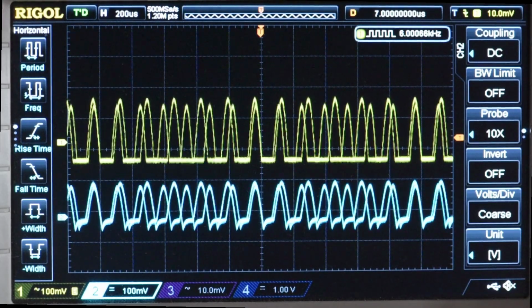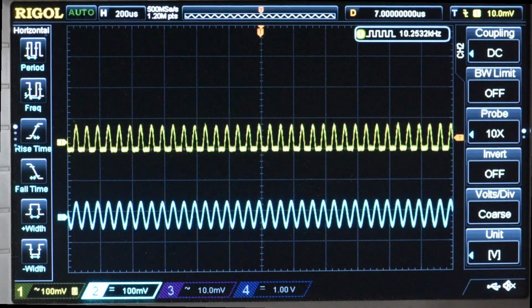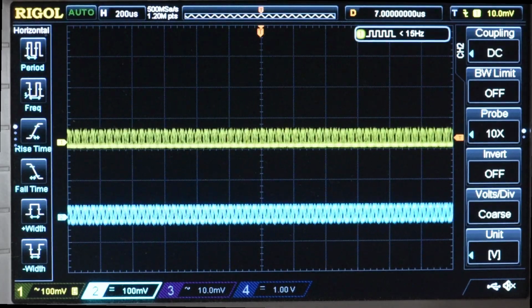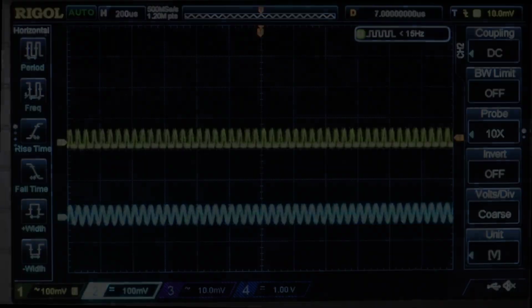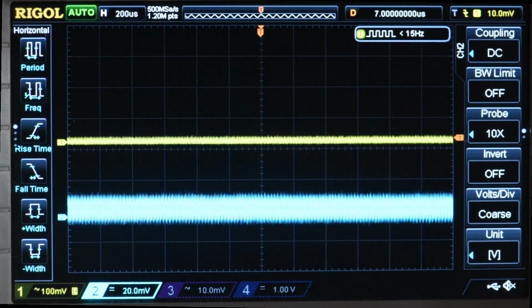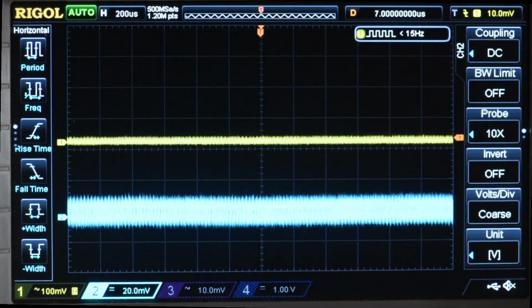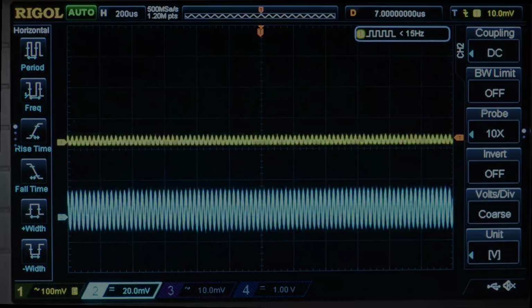That should give me about the same frequency response as the voltage section. The yellow trace is the output of the DAC buffer. This time the blue trace is the input to the ADC. By 20 kilohertz, well down in amplitude. Just the faintest bit showing up in the output at 60 kilohertz. So if I can sample at 120 kilohertz or better, should be okay. Then maybe use a digital filter to eliminate anything over say 25 to 30 kilohertz.